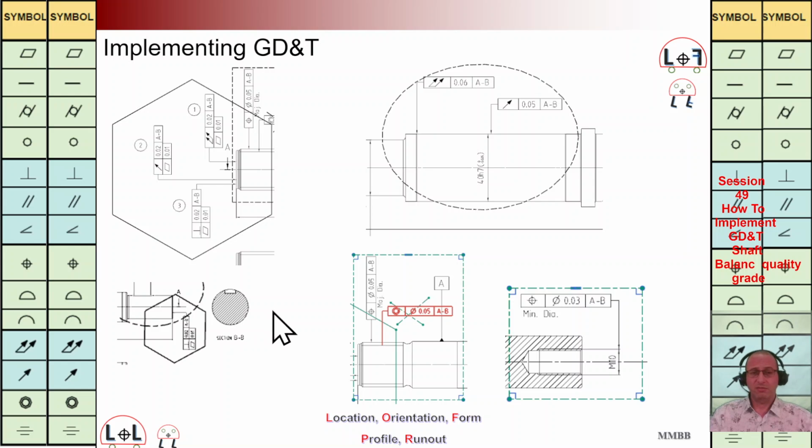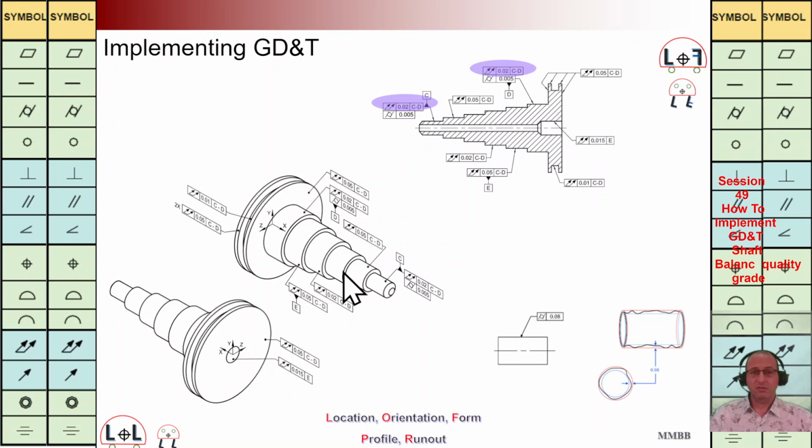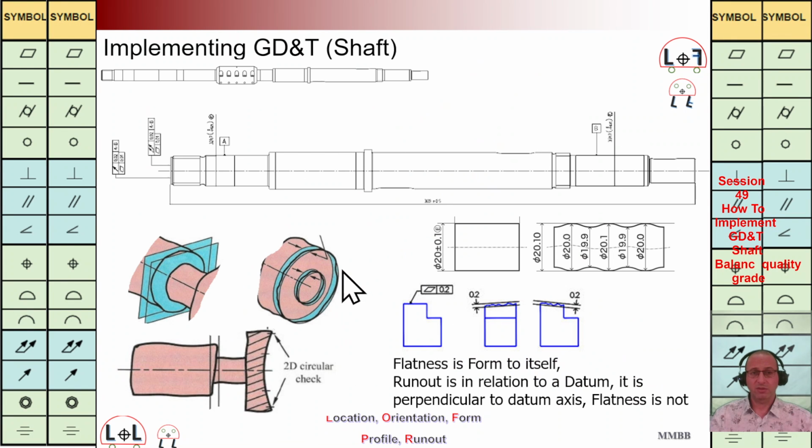And the last item I would like to highlight is reference axis A and B. If you remember, at the beginning we talked about that. We are going to have two bearings here, one here and another here, and we have this surface as a contact surface between shaft and shaft coupling. I haven't chosen this bearing area as reference axis A. I have chosen this one, this contact area.